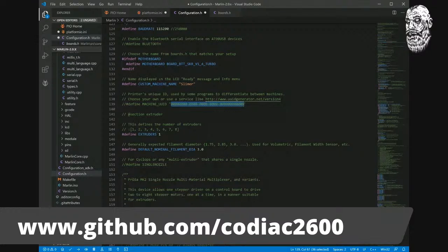So if you have 10 machines running the same brand MKS Gen L, if you try to log in via OctoPrint or Repetier or anything like that, they're all going to have the exact same name. It's just going to say USB 2.0, dash, underscore, a bunch of variables, typically all zeros. You can add a custom machine UUID. That way you can kind of find that.